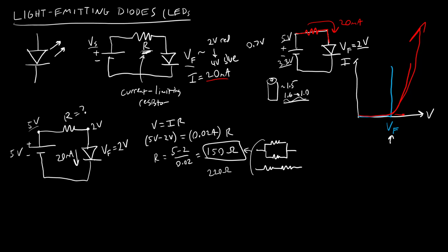That is going to lower this current. But in practice, in terms of visibility to the human eye, you're probably not going to see a huge change in brightness of the LED with that slightly lower current. If you look up an LED datasheet, sometimes there will be a separate graph, not just the IV curve, but showing luminosity against current, so you can see how much the brightness will actually change with the current. In practice, it's going to be visible to the human eye, again, even down in single-digit milliamps many times. So better to play it safe and go up with a bigger resistor as opposed to going down to, say, a smaller 100 ohm resistor, increasing that current and risking burning out your LED immediately or decreasing its lifespan.